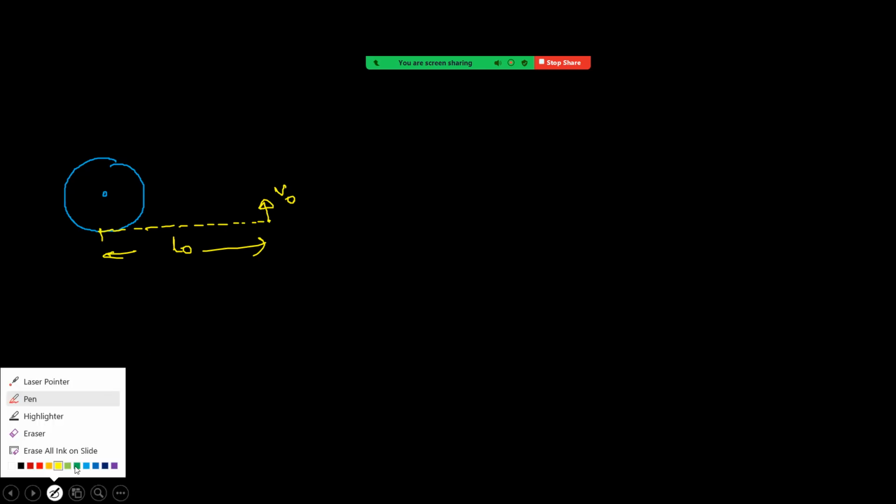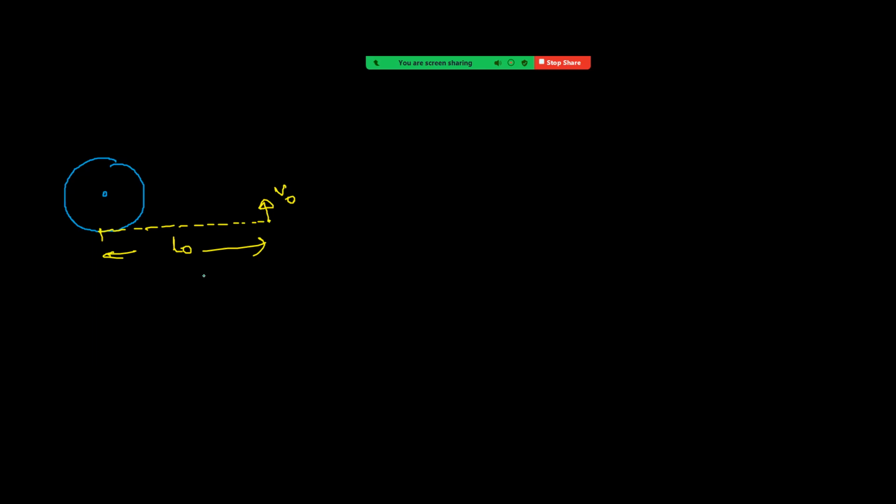If you observe, throughout the motion, the speed of the particle does not change. First focus on the free body diagram for this one. Now this is on a horizontal plane which is smooth. So its weight mg vertically downwards is balanced by the normal reaction vertically upwards. That means in the plane, on the particle, there is no force along the velocity.